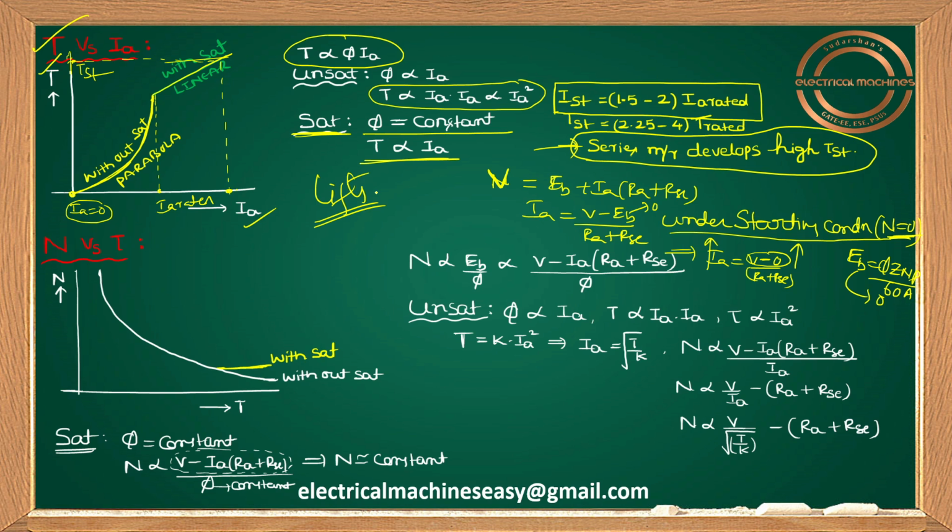So those DC series motors can be used in applications where I need high starting torque, where we want to start loads which are very hard to start and have high inertia. Definitely in DC motor applications, the DC series motor is more preferable.